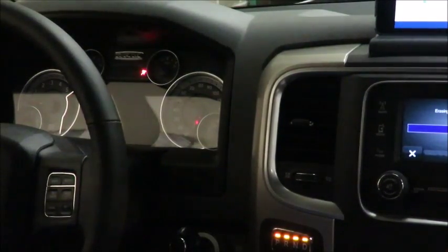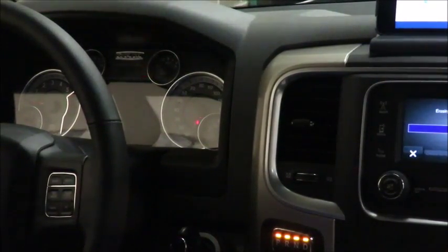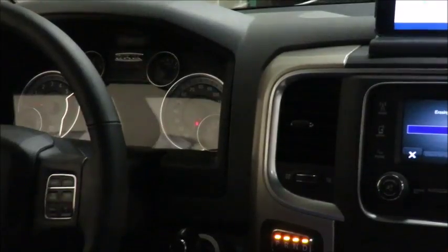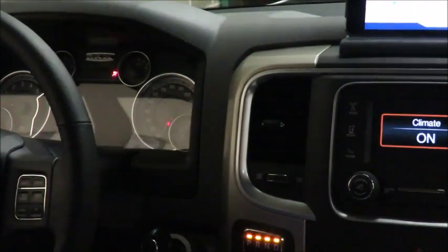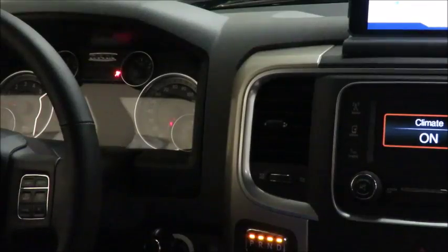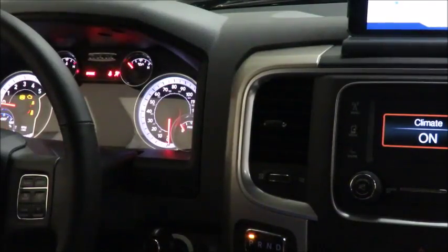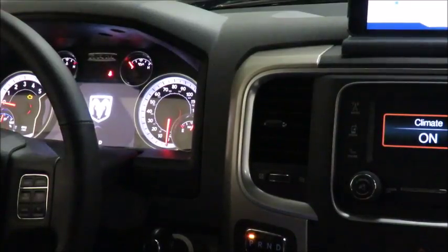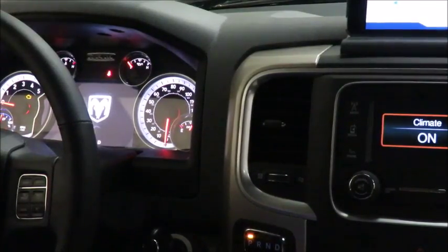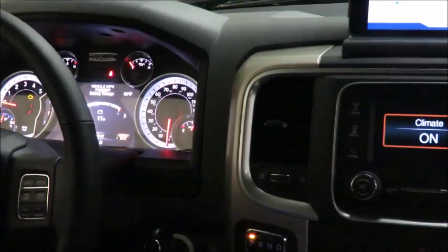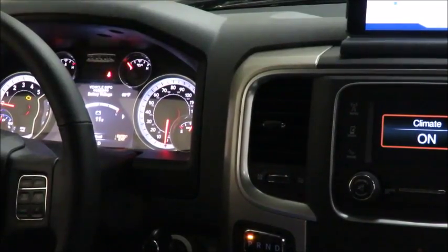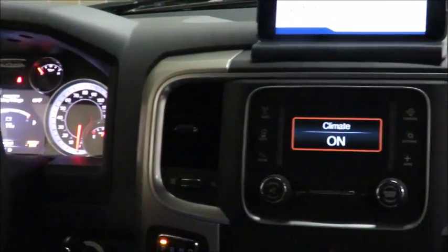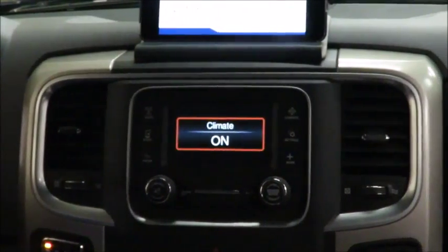You'll notice the OTA application displaying various stages of the update procedure, including erasing the module and flashing the module. The progress is communicated to the OTA cloud, so there is feedback during the OTA event. During the programming session, you'll see the instrument panel dim and then restart once the update has finished. After the reflash has completed, the OTA client will perform any post actions necessary to complete the update.